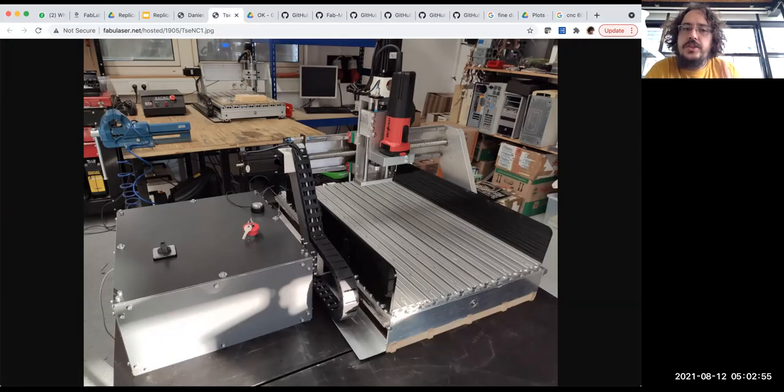You would, of course, change the motors. You would, of course, have a separated motion actuator, so you don't want to put the shaft of the motor directly on the ball screw with a coupler, but you have another belt and pulley. And then for the rest, you increase the size of the shoulders, for example, the thickness of the shoulders, and then you can scale it up as much as you want, I think, like full-size ShotBot.